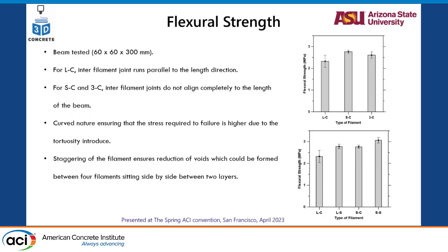We got about 33% increase already in flexure strength. So that's a very good advantage. With the same mortar, same print times, everything remaining the same, we are getting a 33% better response in flexure itself. Now these three also perform quite well, about 25 to 30% increase. Again, for the reasons that I told before, we didn't continue with those filaments.